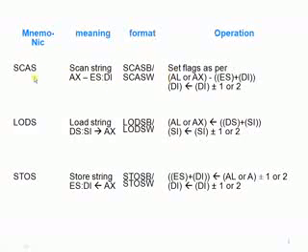Now what happens here is, whenever this instruction is executed, the content which is pointed by the destination will be subtracted from the AX register. Okay, after that DI will be incremented or decremented by 1 or 2. And we have LODS, which is going to load the data from the source to the register. Okay, source is nothing but the location which is pointed by DS and SI. The data will be loaded into AX or AL, and this SI gets incremented by 1 or 2 or decremented by 1 or 2.